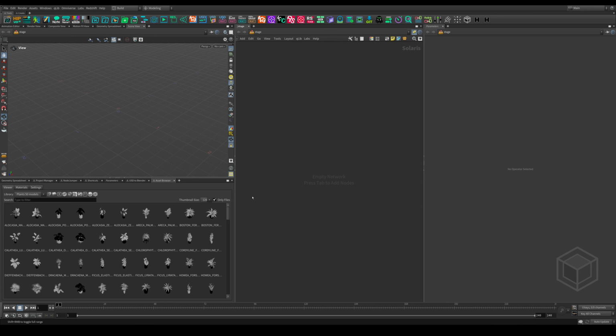Just to show you how that works, we go into the asset browser and we can select any of the models here. If we are on stage, we can just drag and drop it, and it detects that it's an FBX file. We'll be able to import it as a file node and all the following: the FBX character import, FBX skin import, and FBX animation. So we could just put FBX character, and there you go.